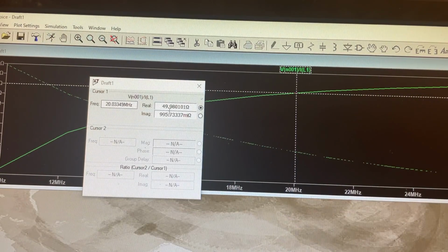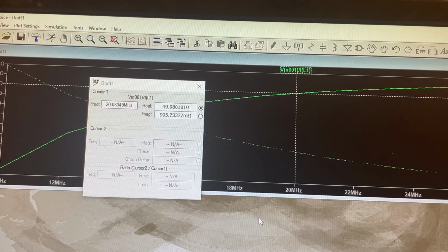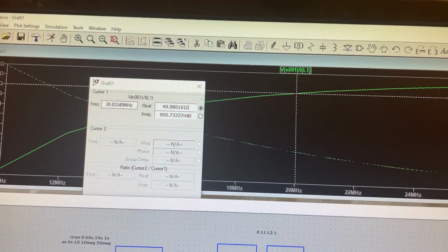And there you see, we're back to about 50 ohms. That would be very, very close to 50 ohms in the center of the scale there. So we're able to transform the impedance from 50 ohms to 25 ohms. We're able to get a match by using a 2 to 1 ratio for the transformer. So that's how a transformer is used to transform impedance.